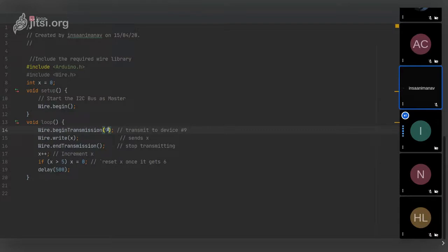And for actually seeing, let's say I have 4 different Arduinos connected and I want to see the address for all of them. Wire.h actually has an example, which is the I2C scanner example. If you run that example on your master, it will read whatever I2C devices are connected and will fetch you the addresses in terms of numbers and hexadecimal codes. So this is what is happening here.